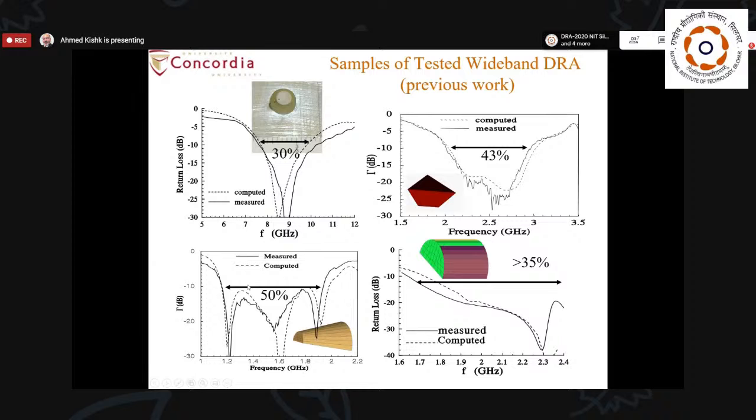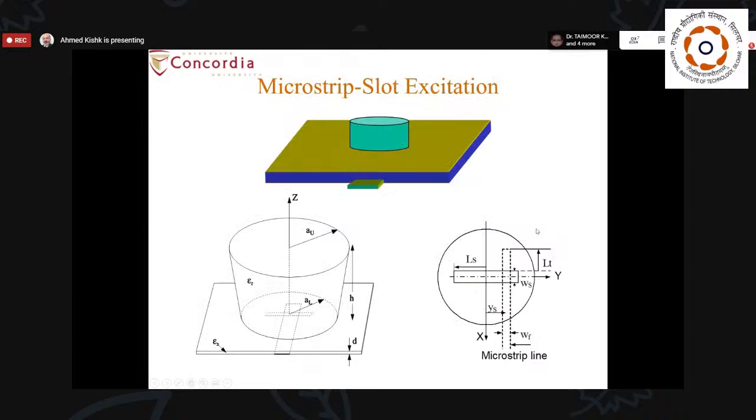So as I always say, we have to use the bandwidths that have the same radiation characteristic or same family of modes, the modes that have the same features and characteristics. If I have the half cylinder as such, one can achieve about 35% that is coming from the mode that has a null on the axis, which is the HEM12 mode.